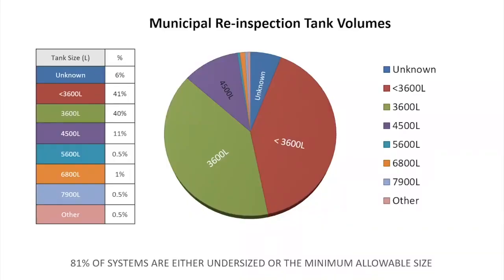When you are pumping out a septic tank, you're not trying to remove the liquid fraction. What you're trying to do is remove the solids fraction that's accumulated at the bottom and at the top of the tank, that ostensibly is making the working capacity smaller. The smaller volume tank has less time that the sewage spends in it. So when you're pumping out your tank, you remove accumulated solids to rejuvenate the tank's capacity. Does this make sense? Okay.